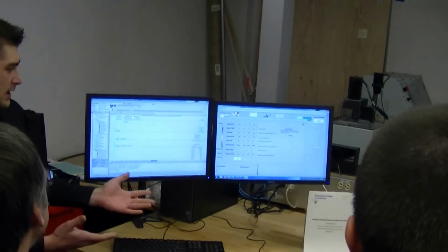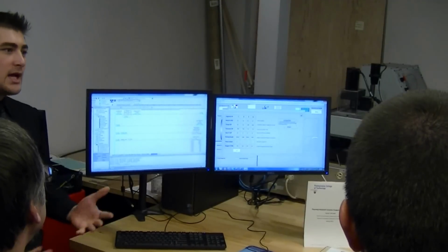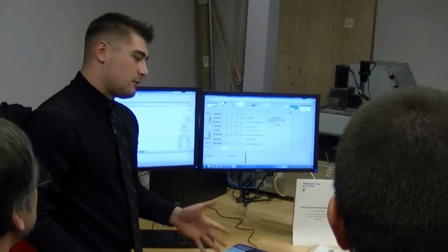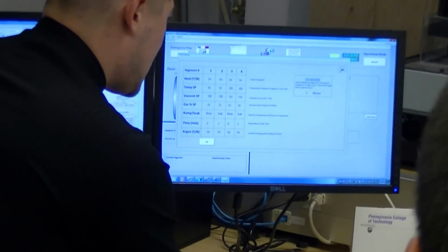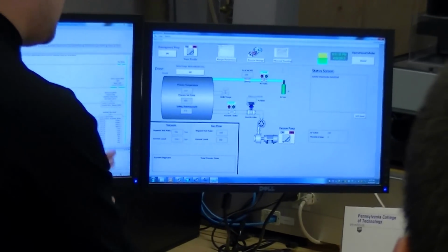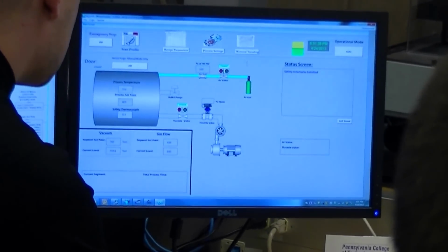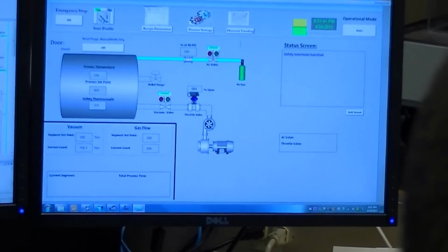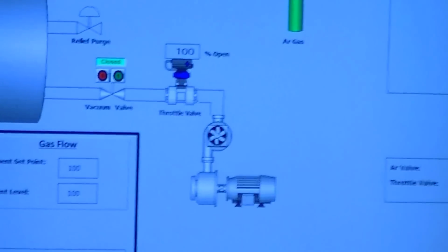So, you know, in these kind of systems, especially recipes, there might be processes that require different times. So this is designed for a specific user interface. And basically, once this is done, the PLC has those values loaded in, and the system is then changed to automatic mode. And then we start this profile. You'll hear everything adjust to its set points, and after 10 seconds, the profile will start.